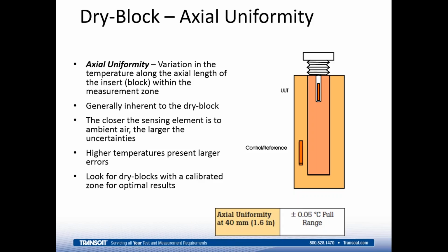When I compare those two together, there's going to be a large uncertainty in the accuracy of my calibration, because there's a big difference between the temperature at the bottom and the temperature at the top. So in modern dry block calibrators, the axial uniformity ought to be specified. For the field metrology wells, you'll see those are all specified uncertainties, so that I can determine, if I'm using a shorter probe, how bad is the error?